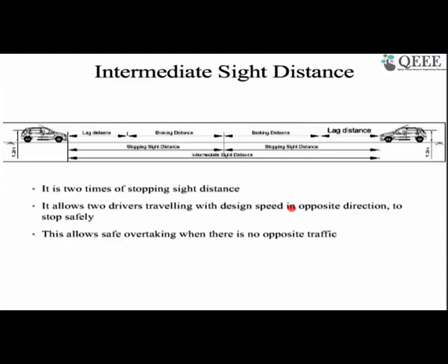Now in this process, you are expected to see the vehicle coming from the opposite direction, slow down, and adjust the vehicle position in such a way that you can safely pass each other. So in this case, the worst condition is that both vehicles need to stop. If both vehicles need to stop, it means you need to provide the stopping distance.